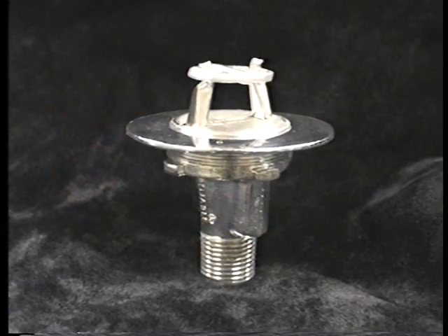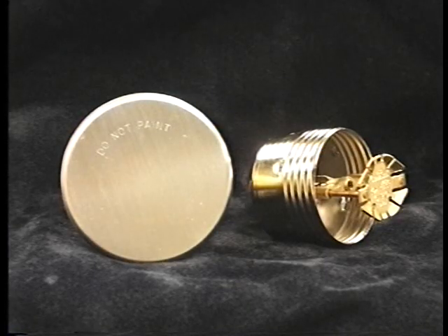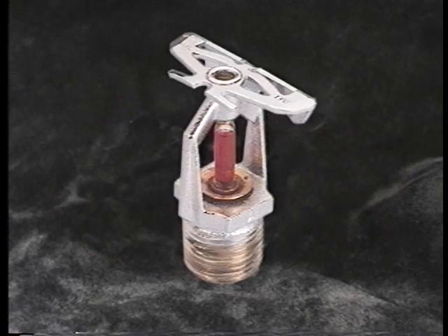A flush sprinkler positions the majority of the sprinkler above the lower plane of the ceiling. A concealed sprinkler is a recessed sprinkler which has a cover plate installed so that it is generally at the same plane as the ceiling. In a fire situation, the cover plate falls off before the sprinklers operate. A sidewall sprinkler is intended to be installed along a wall and has a special deflector designed to discharge most of the water outward from the wall.